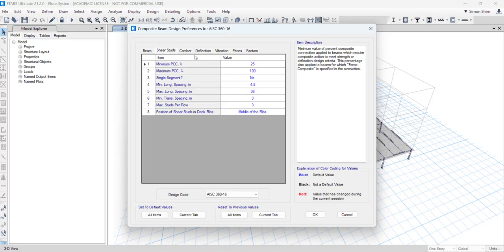The top of the beam will experience compression, the bottom of the beam tension. Since we tie them together, most of the compression stress will develop in the slab and some tension in the bottom side of the beam. So that's why we can maximize the strength and stiffness by using this composite action.